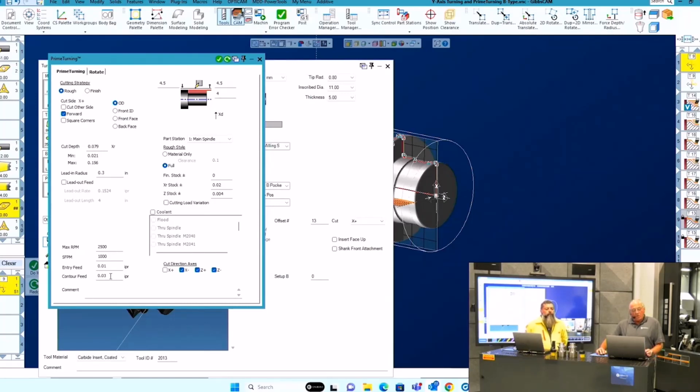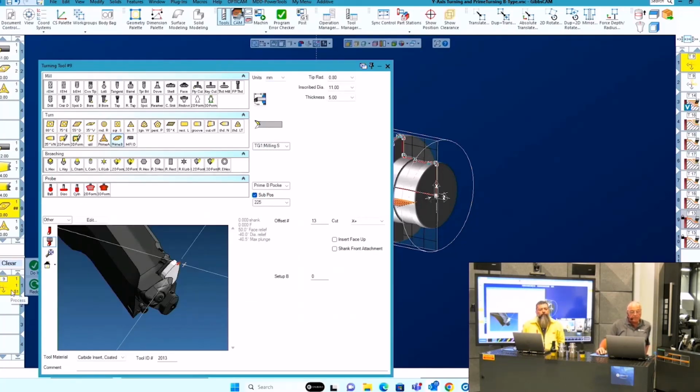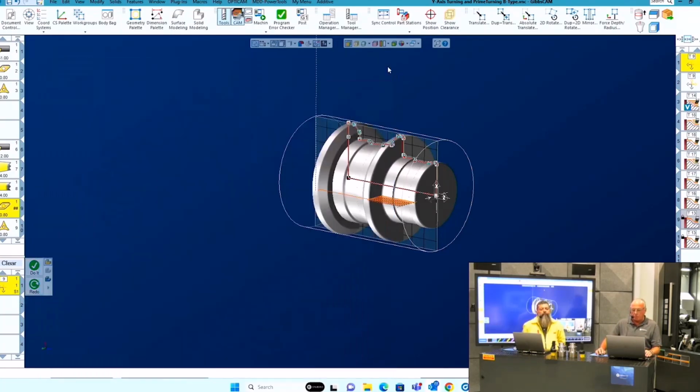They are aggressive. We could go bigger, but they're not very conservative either. So they're pretty aggressive, but there is still room for going faster in the feed rate per revolution. And if you leave some stock, it's X 20,000 and for the C stock 4,000. And then how I approach my part, like clearance and the stock size. So whenever you select a tool, it also allows you to select whatever you want to do, a roughing, a finishing, a tool pass, is it milling or turning, pretty much always the same thing.